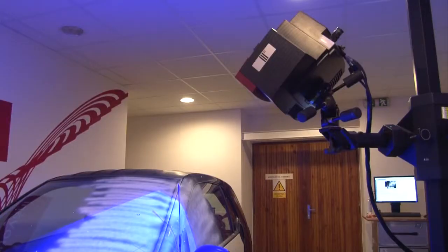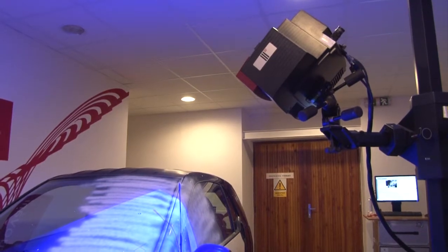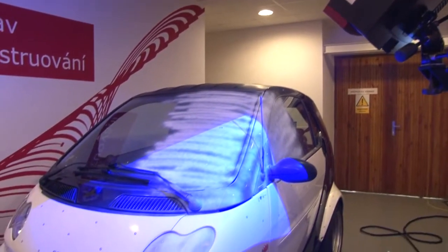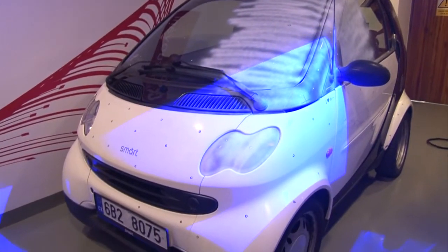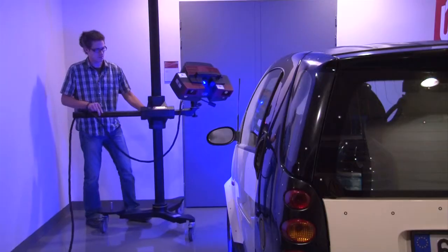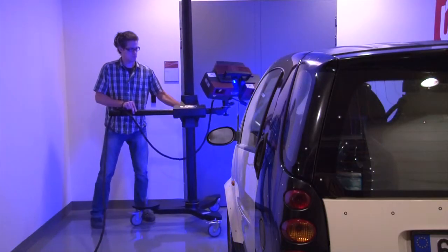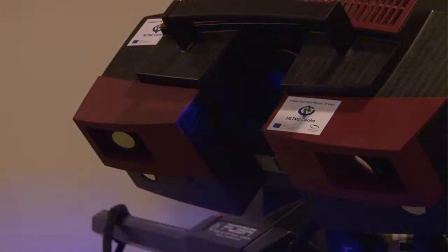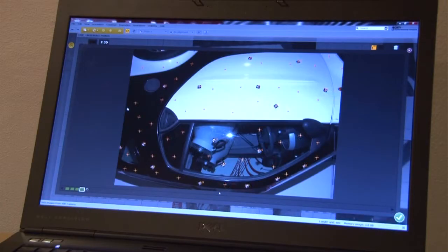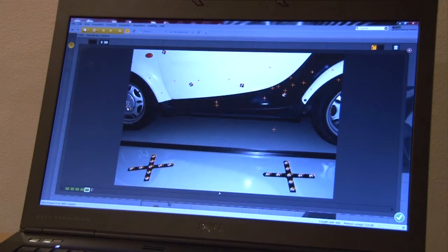Photogrammetry is often used as an input measurement for 3D scanning. The 3D scanning is then much faster and it achieves greater accuracy. Photogrammetry is often used, for example, when a request comes in for a quick measurement of sizable objects, or if there is a need to measure shiny or transparent surfaces.